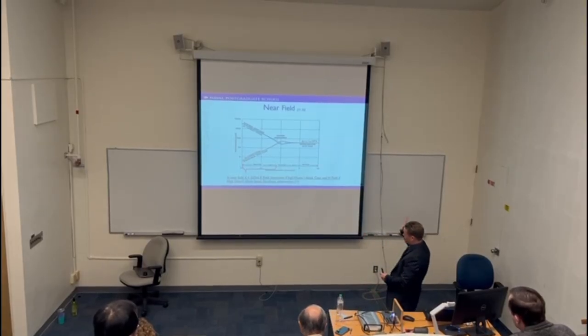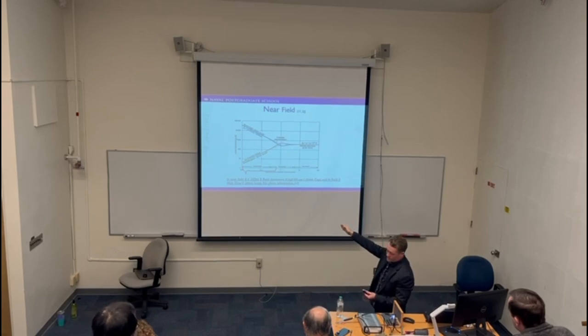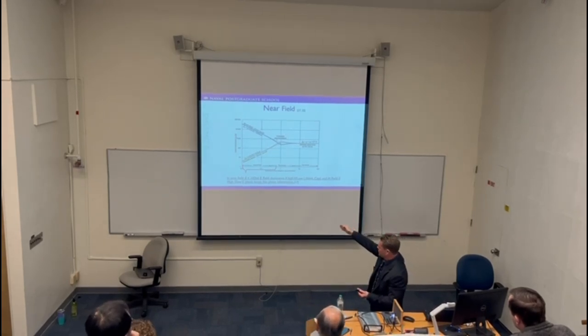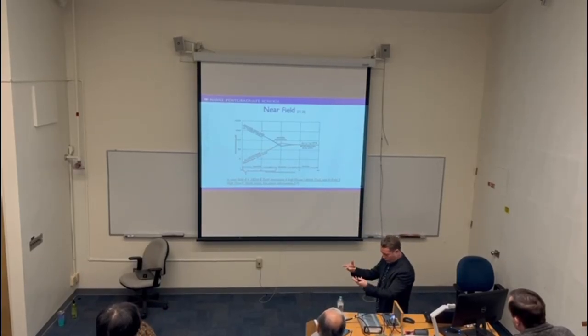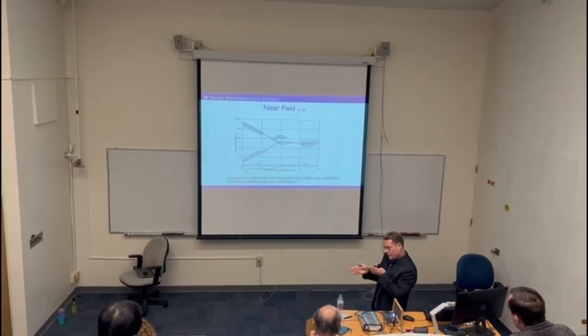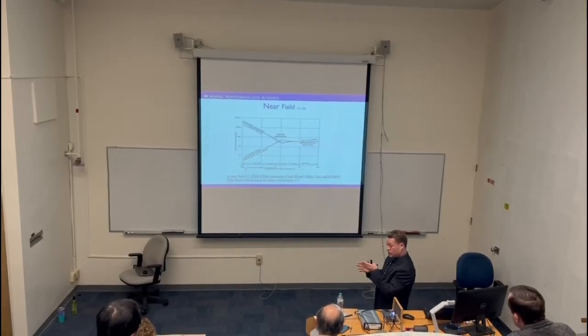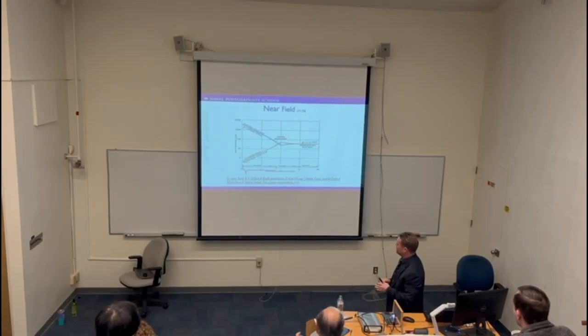As soon as you get to the far field, where the threshold is lambda, the wavelength, over 2 pi, now you're actually getting a transverse electromagnetic propagating wave, where the E field and the H field are orthogonal to each other and in phase. Traveling through space, you can divide the two and get approximately 377 ohms. So the near field, let's just say, is quite nuanced.